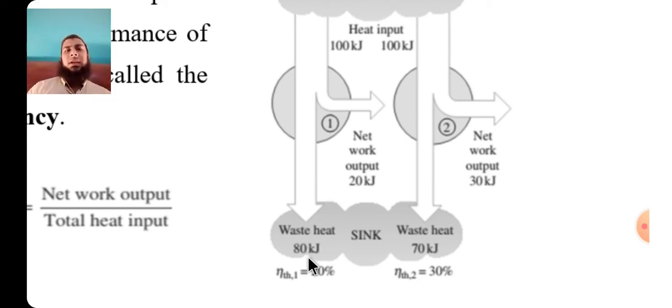Like in the Rankine cycle, we see that heat is released in the condenser, where after the turbine we have flash steam. So we have two options: either pressurize it and then feed it to the turbine, or convert it into water and feed it through a pump. Pressurizing gases is a very expensive method, so we lose all the energy in the flash steam and convert that steam into water. That water is fed through a pump to the boiler, and from the boiler to the turbine, and the cycle goes on. So in a practical system, that kind of energy is lost to the environment.